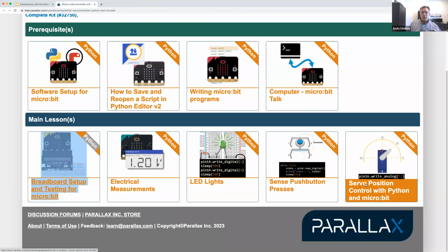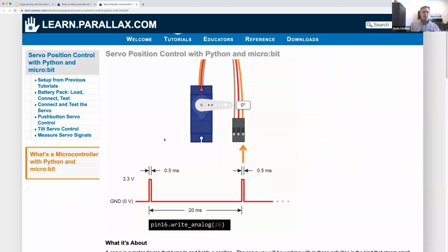What's more, you can even use the microbit as an oscilloscope. So here is an example of the very brief light on signal and the amount of time it lasts that controls a standard servo and what direction it points to and holds with its armature. It's called a horn in hobby electronic speak.